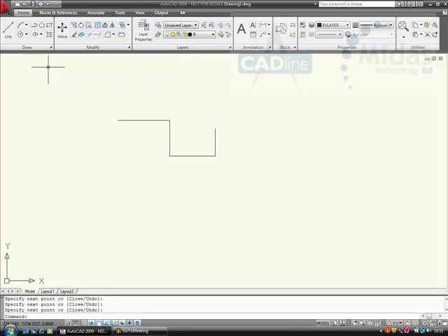I also have an extended area at the bottom, so you'll see the word Draw and an extended arrow. When I click on that, it will give me the Draw toolbar, as you've previously known it in AutoCAD. And the same with Modify. I've got the Modify toolbar here, extended to Modify. So again, quicker ways of finding my way around the drawing.